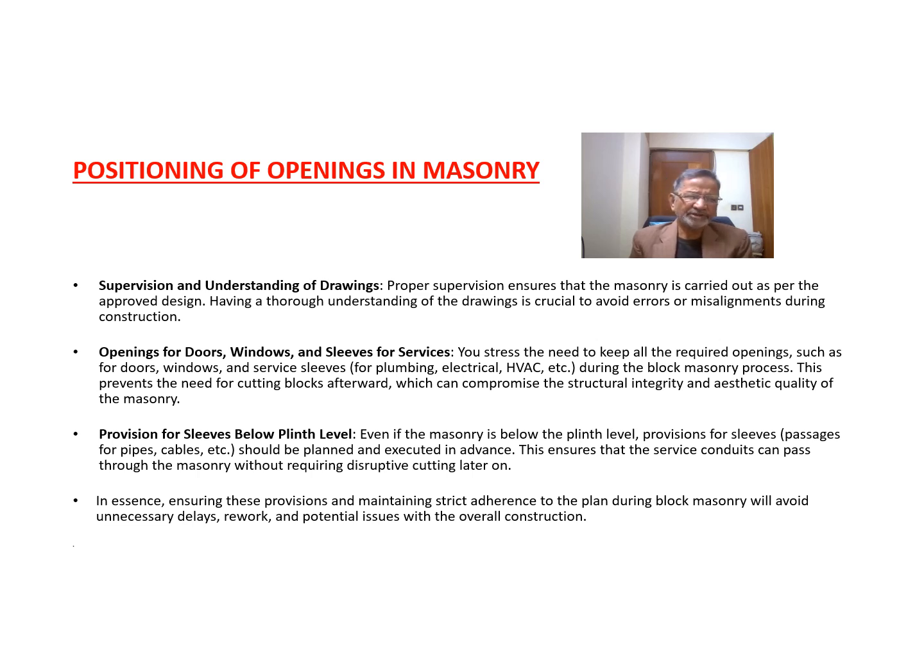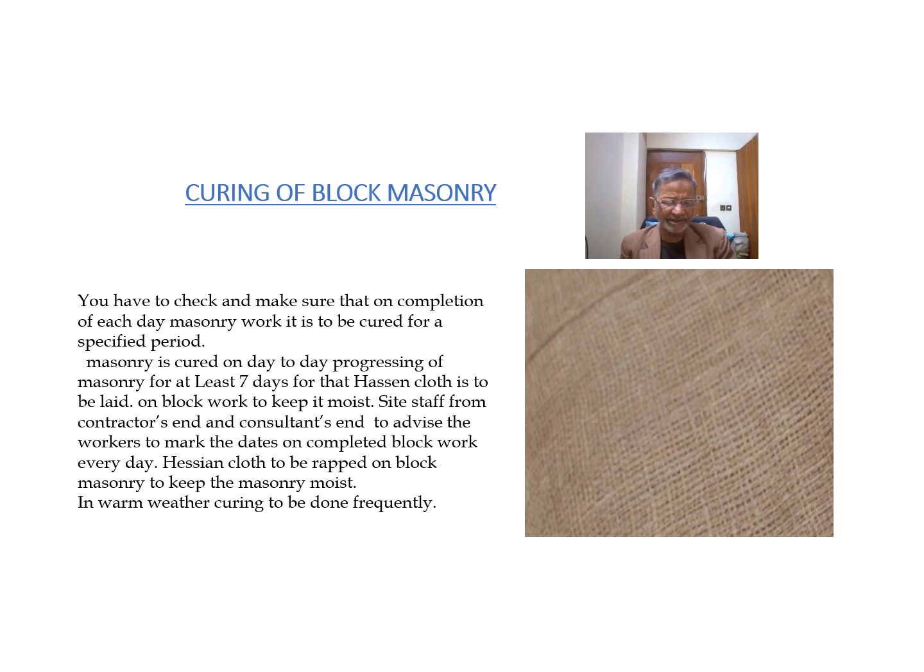For all the openings, there should be a gap on all the sides of the opening for fixing the doors, windows, and ventilators easily. Dear viewers, especially the engineers at site, they must know that curing should start from the next day, not immediately after the completion of the masonry.